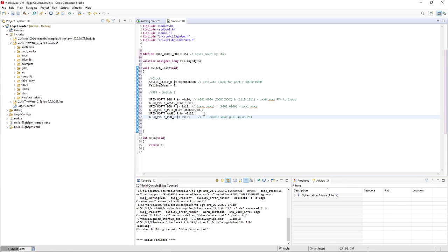What this pull-up resistor is going to do is ensure that the voltage is always high, because we want to trigger our interrupts later on falling edges. The way we want to do that is to have the buttons be a high voltage, and when pressed it will go low. That will allow us to see when the button is pressed and trigger an interrupt, which now we can go talk about.